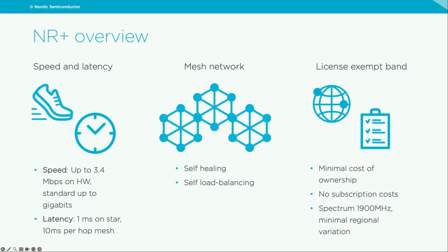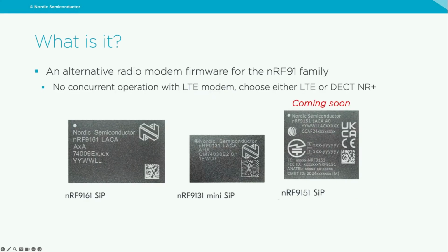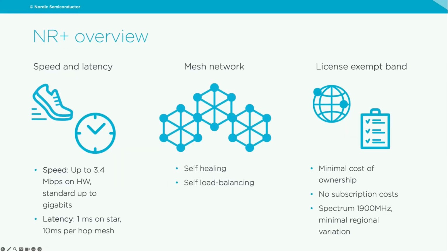Mesh network is a very key concept in the standardization, seen for the self-healing and self-load balancing features that can be achieved. Of course, the network extends itself with every node added in a mesh network. The range increases, but also the error correction: if there is a change in the environment and a radio link goes bad, then the devices can scan for additional or alternative parents and switch the routing mechanisms.